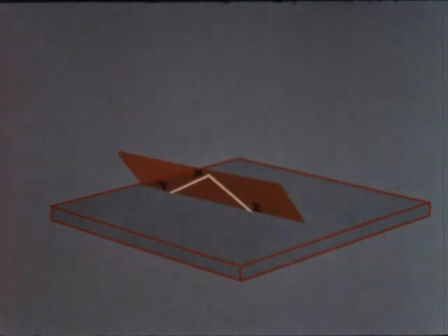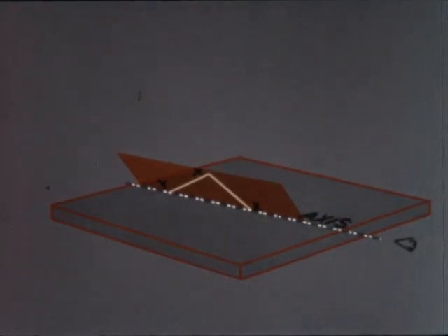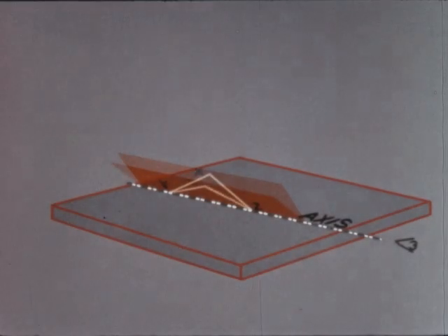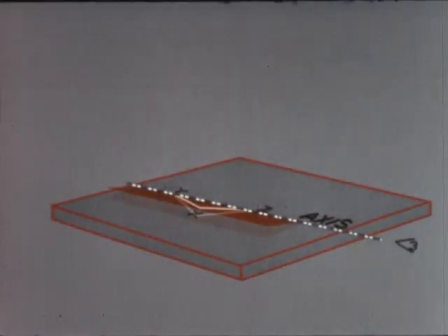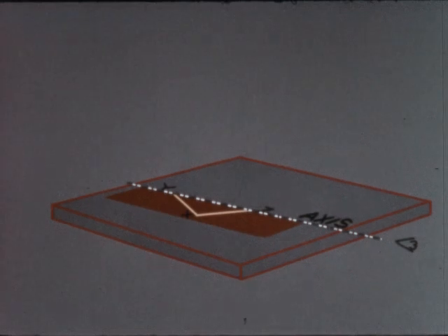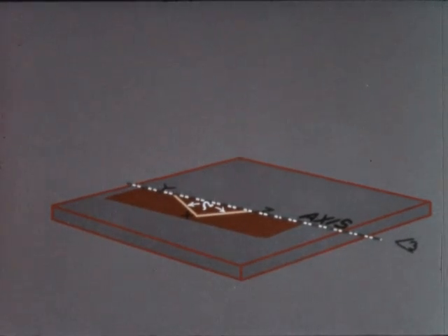When the measuring plane is revolved about an axis containing points Y and Z, the true size of the angle between XY and XZ will be seen in the top view. This is the dihedral angle between the two planes.